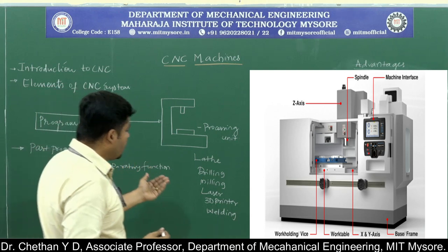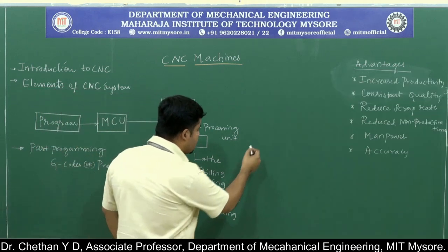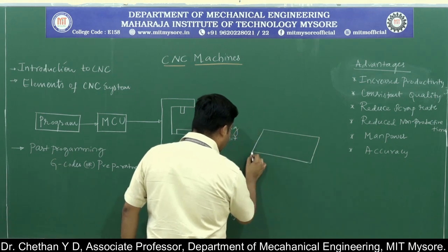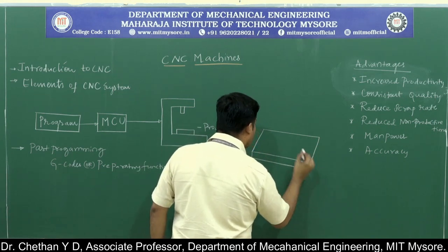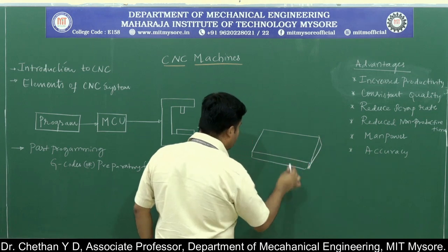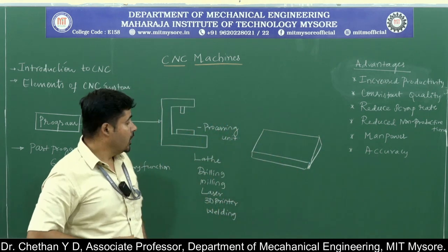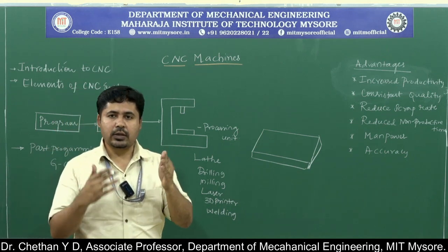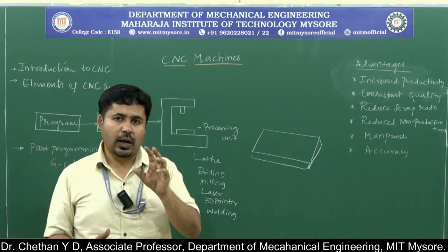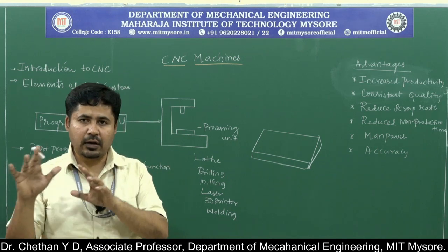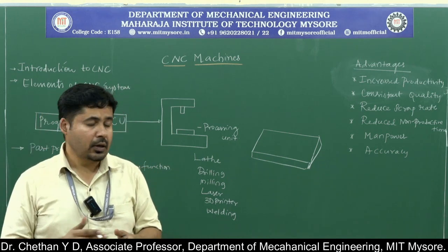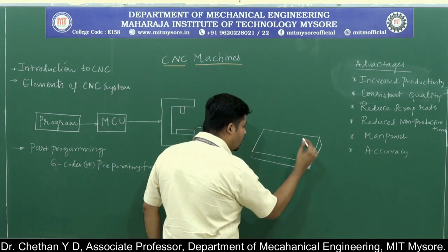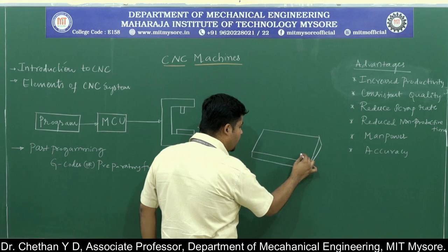Similarly, you can have the milling machine. Let us take a particular workpiece or job, wherein we need to cut a particular slot. For that we have to have different codes like G codes and M codes. These, and sequence numbers, are responsible for writing the syntax of that particular program, wherein the milling cutter has to reach from the coordinate system to the desired point.